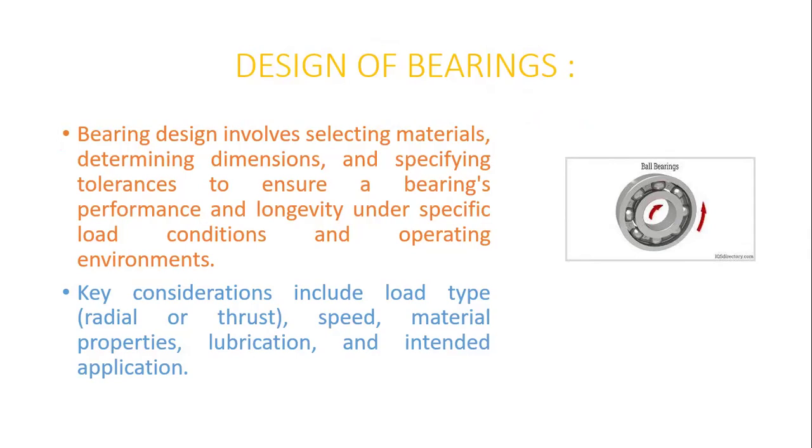Among all, the most important key factors are load types, speed and material selection, as well as the lubricant materials that are used to control the friction between the moving parts. Let us see the further information in the following slides.